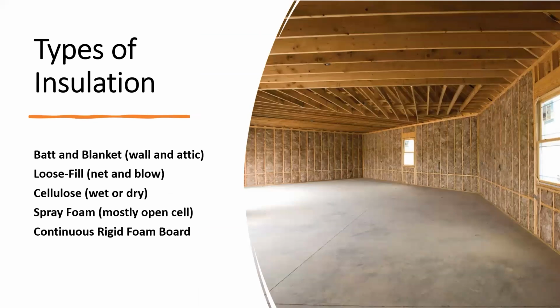So, the type of insulation that we see, it doesn't really matter what type of insulation is used. What matters most is the R value per inch and how well it was installed. The worse it's installed, the worse the R value gets. But also, to quote the book, it says permanently installed, not temporarily, not just, well, it's going to hold in place. It's got to be permanently installed.